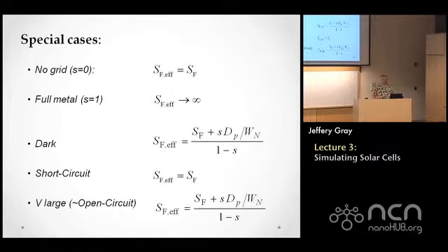But at open circuit voltage, it would be a different number, which would be a combination of whatever that free surface looked like. And basically this term here is sort of the effect of the metal on the surface recombination velocity. What we found when we did simulations is that you're pretty well off, even though you're not going to be right at short circuit exactly.